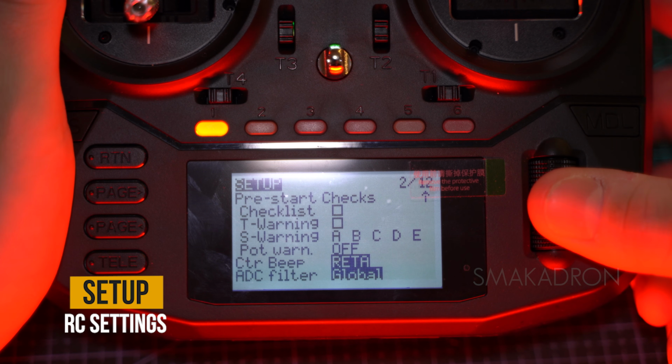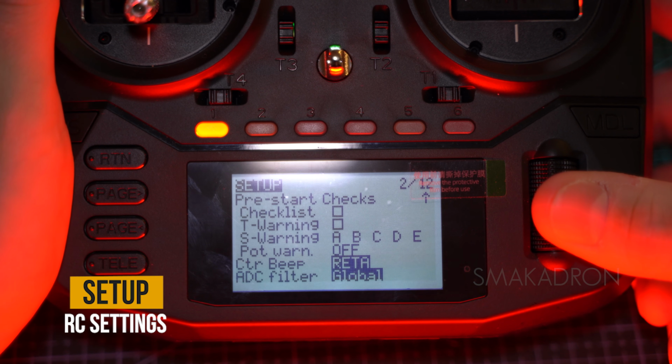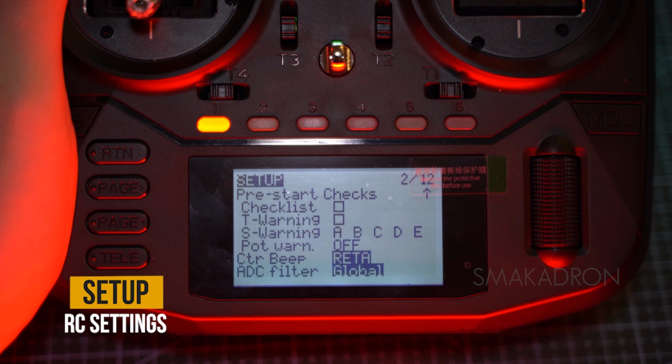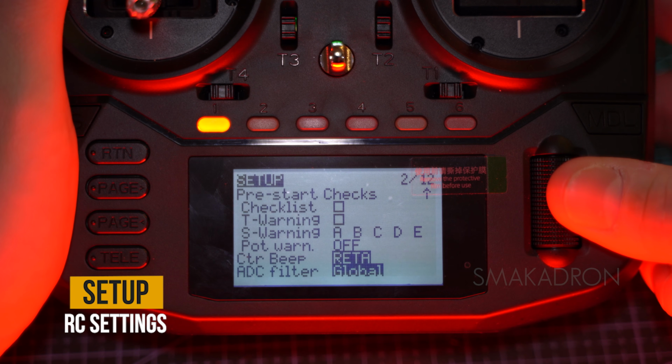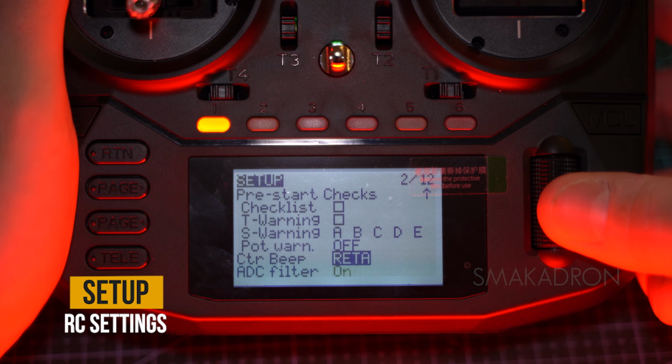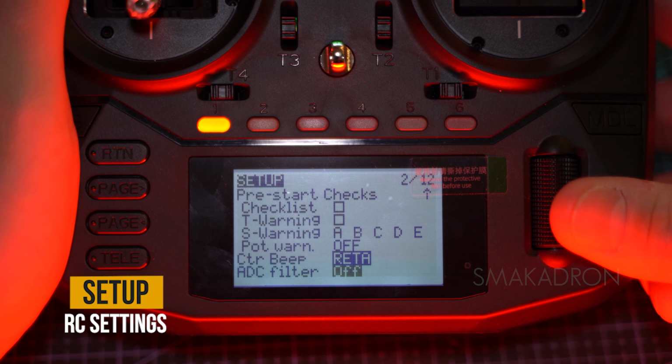The ADC filter, analog to digital filter, is used to process signals before they are converted by the analog to digital converters, ADC. It's a crucial element for improving signal quality and reducing noise. The ADC filter is designed for proportional channel sticks, potentiometers, and sliders, and smooths out small, fast movements caused by electronic noise in the system. Until Betaflight version 3.5, it was a useful function for drones and planes without a flight controller. For models with flight controllers, this filter is usually turned off, as flight controllers handle analog signal processing themselves.